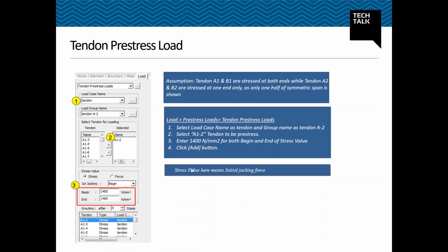And talking about the tendon pre-stress load, we can specify the jacking stress in the form of force as well as in the form of stress. So we can apply the jacking force, and we can even do the sequential stressing.